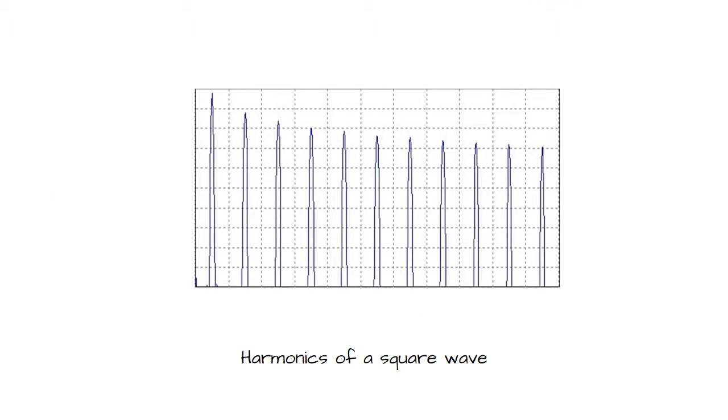I mentioned that square waveforms produce unwanted harmonic frequencies. Here's an example of what harmonics look like. Harmonics are frequencies that are multiples of the fundamental frequency, or the original frequency at 50 or 60 Hz. 60 Hz harmonics would be 120, 180, 240, 300 Hz, etc. These harmonics, if not properly filtered, can be amplified in a speaker system. It is also possible to hear a high-pitched noise coming from the inverter.